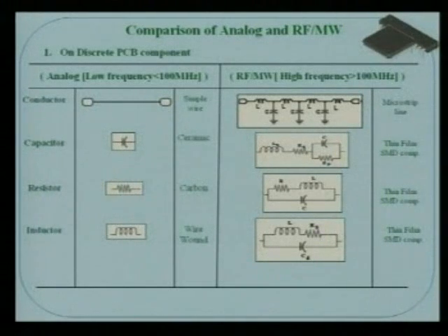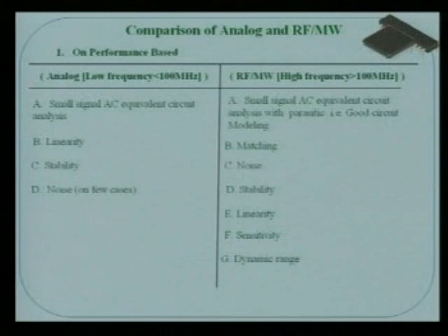So while modeling those components, you have to take care of those additional parasitic components. That is the major challenge of RF design: not-so-simple or innocent components have certain parasitics and certain models that you have to include to capture the real effects of introducing those passive components. This is one challenge in the system.